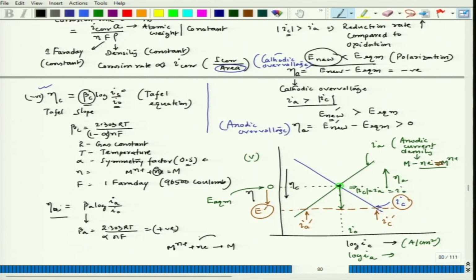So, if we send more electrons, the reaction should proceed this way. When we proceed with the reaction this way, what does it mean? I am consuming metal ion and then depositing it as metal, which is not corrosion, but rather protection. We are not allowing the metal ion to be stable there; it has to go back and deposit on the metal surface.